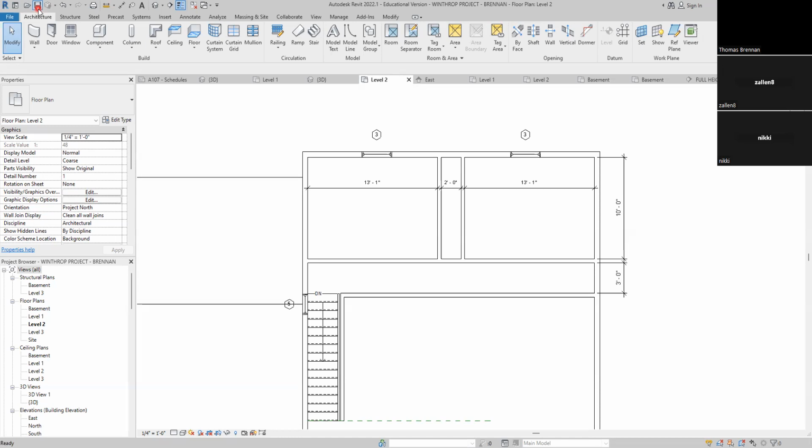Okay, now we don't want that to move. So click on the modify arrow. And one of the cool things you can do here, if you don't want something to move, go to modify. And there's this pin. You click on the pin right there, pin that wall. Just pull it down a little further. Okay, did you get it? Hit the modify, see if you got it. Hover your cursor over that, click on it.